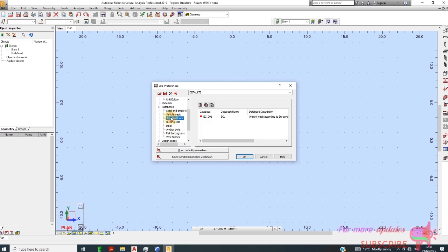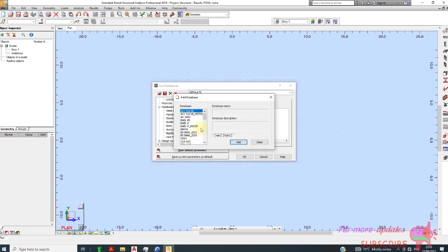And I'll go to standard loads, Eurocode, building soil. Change to that. I want to leave soil data metric. Reinforced bar, and just add BS, I think BS 4449 is okay. And close.